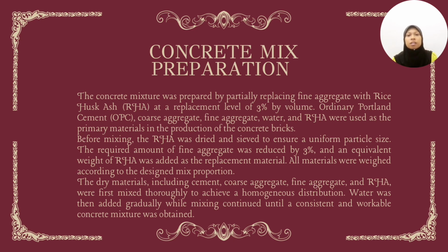The dry materials, including cement, coarse aggregate, fine aggregate, and RHA, were first mixed thoroughly to achieve a homogeneous distribution. Water was then added gradually while mixing continued until a consistent and workable concrete mixture was obtained.